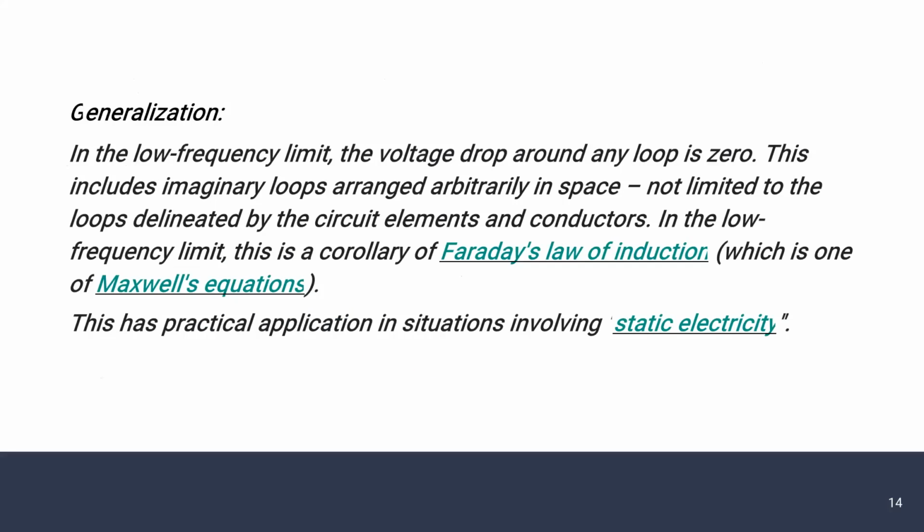Generalization. In the low frequency limit, the voltage drop around any loop is zero. This includes imagined loops arranged arbitrarily in space, not limited to the loops delineated by the circuit elements and conductors. In the low frequency limit, this is a corollary of Faraday's law of induction, which is one of Maxwell's equations. This has practical application in situations involving static electricity.